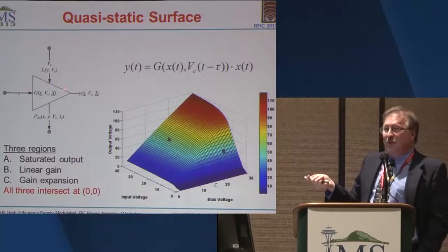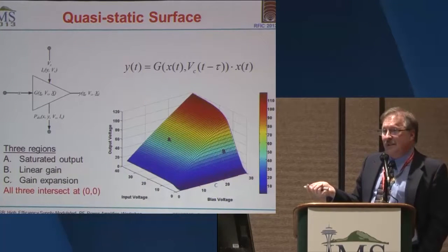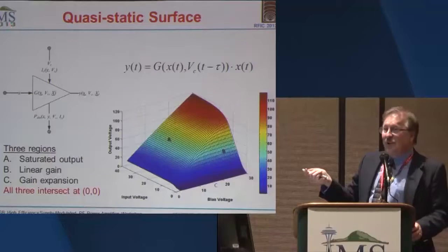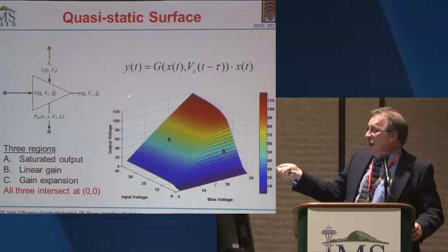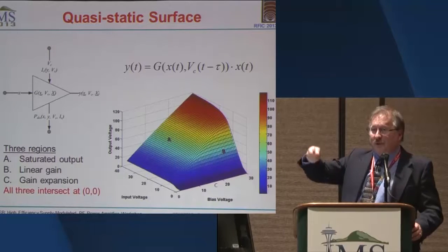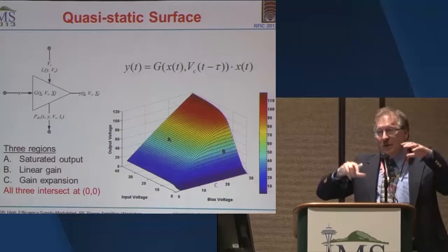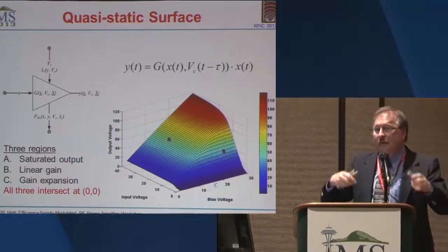The current here, if this is a switch mode PA, will go to 0 down here in this C region, which means the load that the supply modulator is presenting is also getting pulled, not necessarily by the load pull happening over here, but more just the natural behavior of the RFPA. And so you're getting multiple dynamic loading events going on simultaneously here.